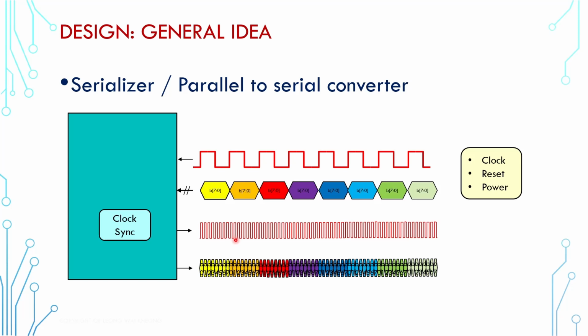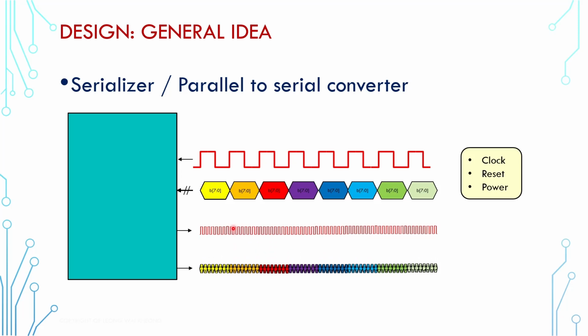If we extend further, a fast clock consumes more power. One way to reduce power is to use a lower voltage for the fast clock. That creates a 2 power domains design, and it requires level shifter to interface between the 2 power domains. Well, we can go on and on, but the general idea is we can extract many design information by simply looking at its clock domains. This kind of skill set will allow us to plan a thorough validation for the design.